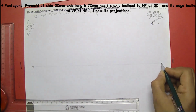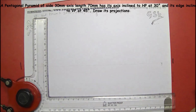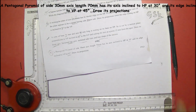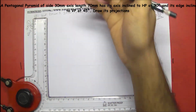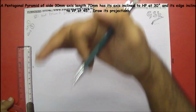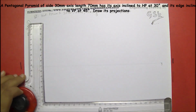This is our main reference line XY, and here I'll be drawing the top view of the pyramid first, because whenever you are drawing solids you have to draw the top view first, because in the top view we'll be getting the true shape of the base. So for that reason we have to draw the true shape of the base first. In this condition we'll be obtaining the true shape of the base in the top view. Next, the front view will be the height of the solid.